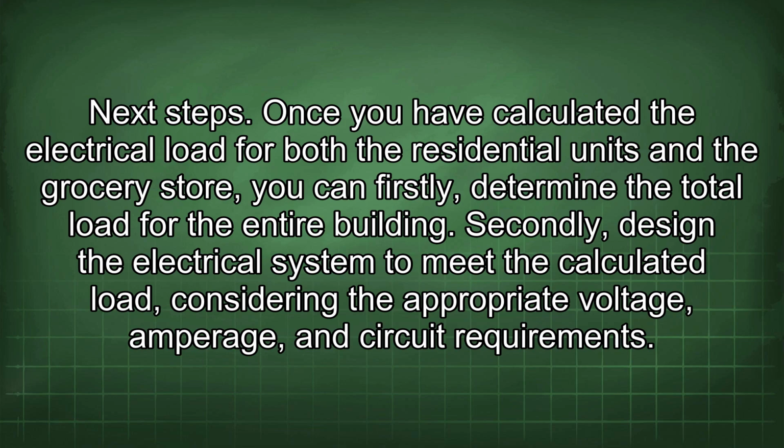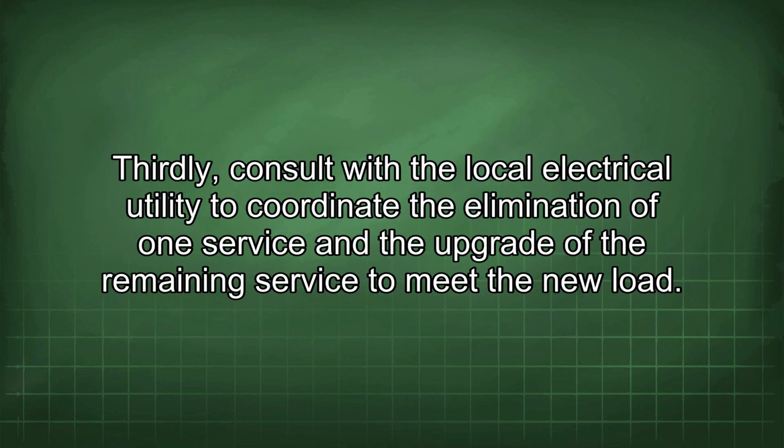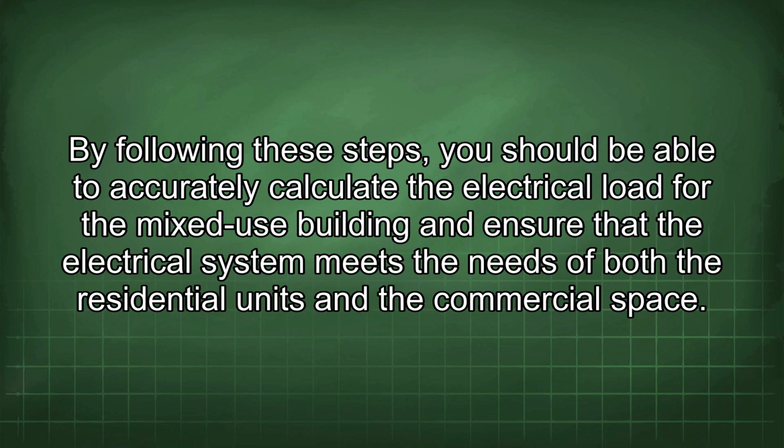Secondly, design the electrical system to meet the calculated load, considering the appropriate voltage, amperage, and circuit requirements. Thirdly, consult with the local electrical utility to coordinate the elimination of one service and the upgrade of the remaining service to meet the new load. By following these steps, you should be able to accurately calculate the electrical load for the mixed-use building and ensure that the electrical system meets the needs of both the residential units and the commercial space.